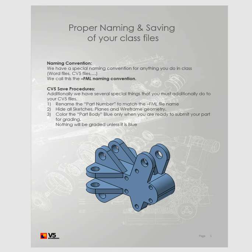And then the saving procedures for Catia that we're going to walk through, we'll do a little interactive video here, is to first, of course, rename the file name, and then rename the part number within Catia to be the same as the file name. Hide all of your sketches, planes, and wireframe, and then the last thing, before saving your part, is to color it blue.